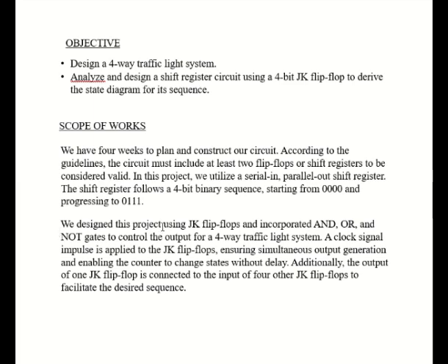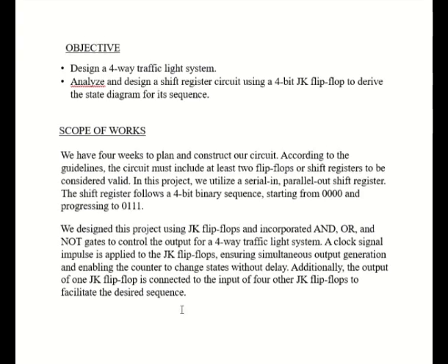We designed this project using JK flip-flops and incorporated AND and NOT gates to control the output for a 4-way traffic light system. A clock signal impulse is applied to the JK flip-flops, ensuring simultaneous output generation and enabling the counter to change state without delay. Additionally, the output of one JK flip-flop is connected to the input of the other JK flip-flops to facilitate the desired sequence.